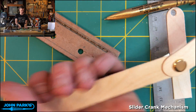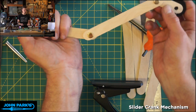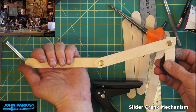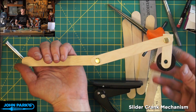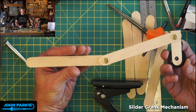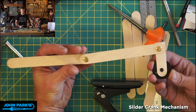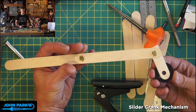And so now, let me pop back out to this camera. Now you can see the pivot of the crank is in line with the pivot of the slider here with a guide. So we'll build a little guide. Then as this rotates, it will take that rotation and turn it into that linear force.